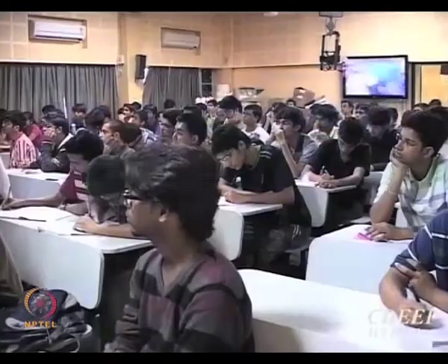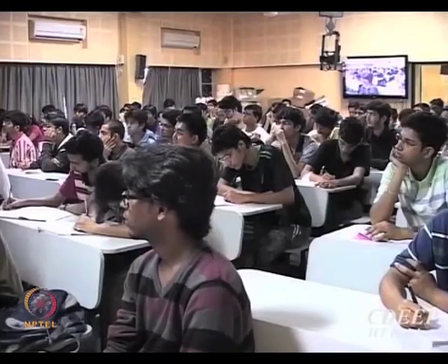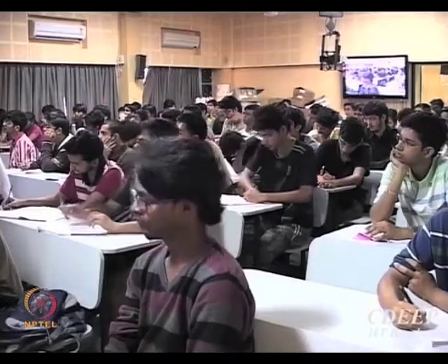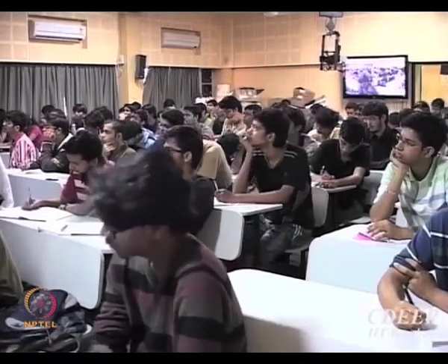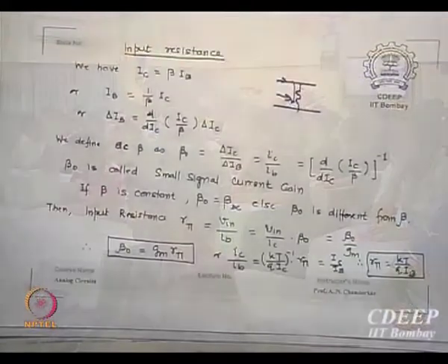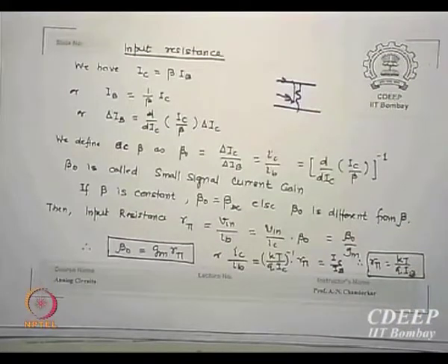It also will be limited by the currents which you are passing, the levels of current. Beta falls as current increases. As IC starts rising, beta will start falling. Initially, as collector current rises, beta will rise. Study the physics again. It will become constant for a great time, and if you further increase IC, it will start falling. Because of the emitter efficiency and transfer factor effects, and temperature effects, beta is not constant.